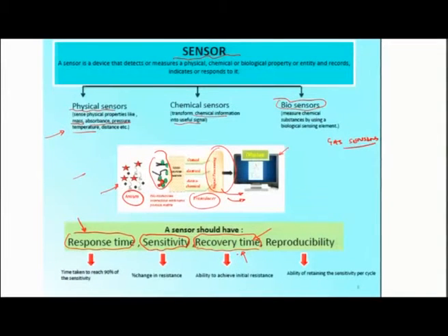In gas sensing it is very important that the response and recovery times are short, because we are talking about an element which changes properties, does some transduction on the presence or absence of certain molecules of gases, and when the molecules are not there in the system, the sensor should be able to recondition itself back to its baseline value and be ready for measurement for the next cycle when the molecules are present. So it's very important that recovery time scales be shorter.